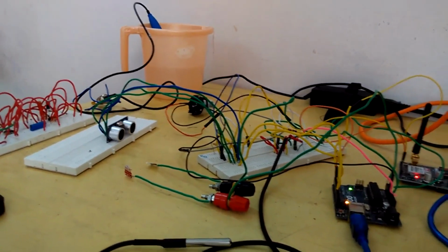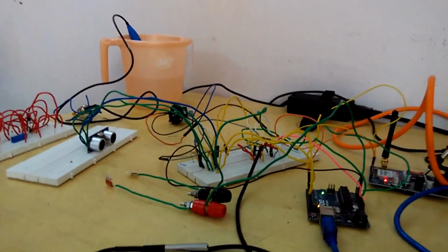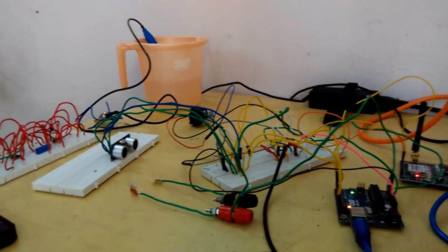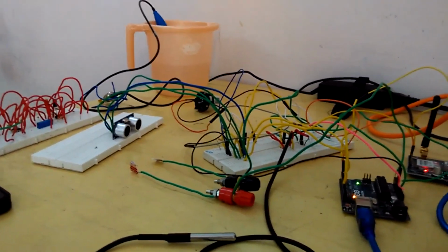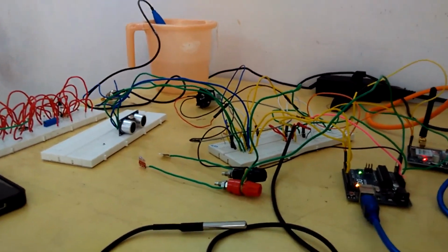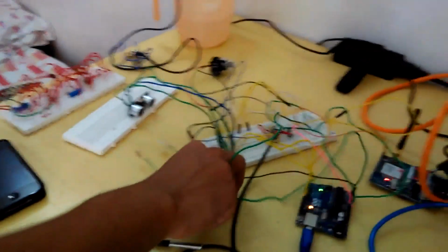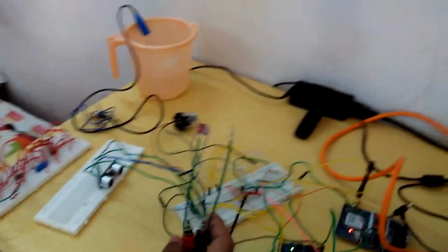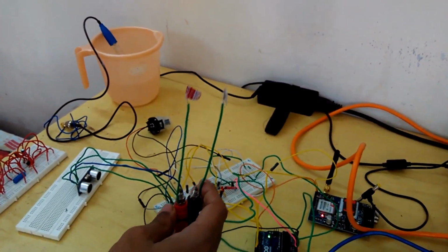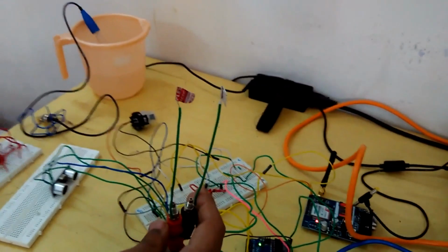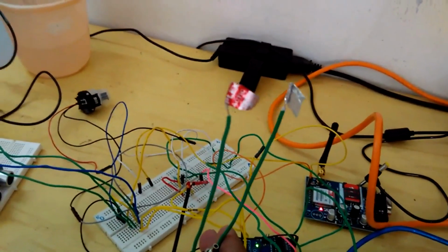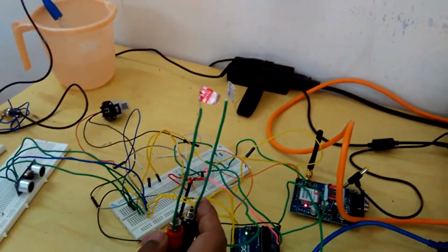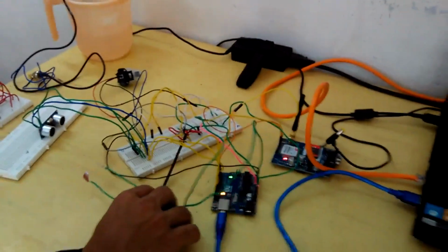Because of the resistances we have attached in the circuit, there's a voltage divider relation, and the voltage captured between the two areas gives a corresponding value depending on how conducting the solution is, so the amount of ions present in the solution. That is how we map conductivity to a specific voltage.